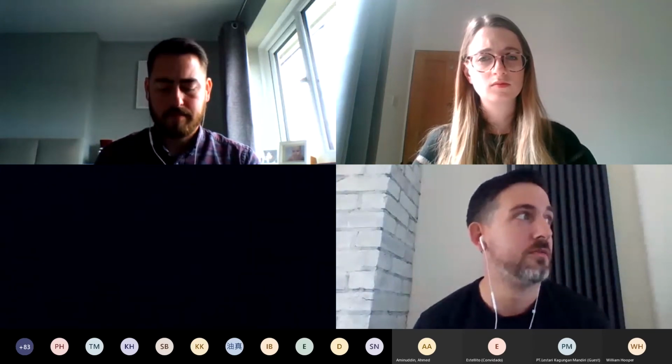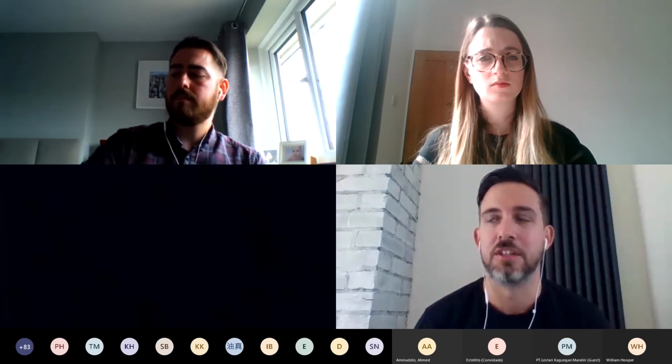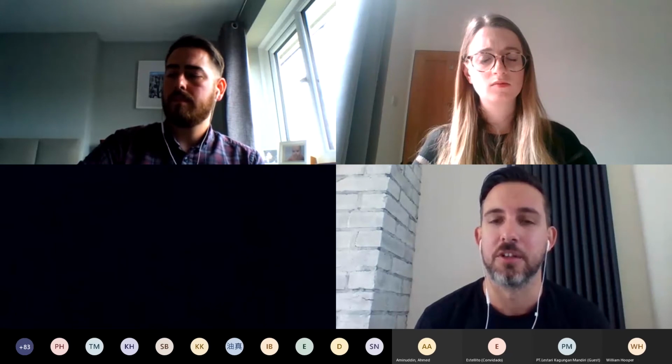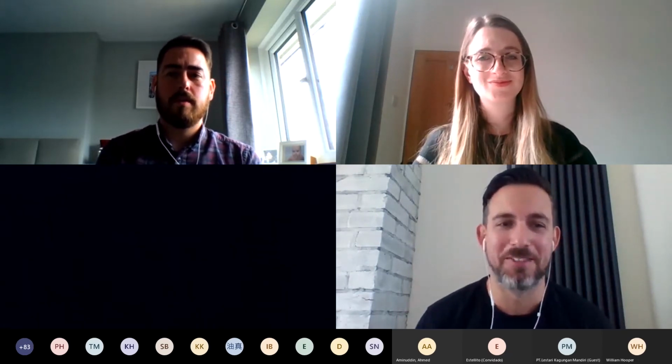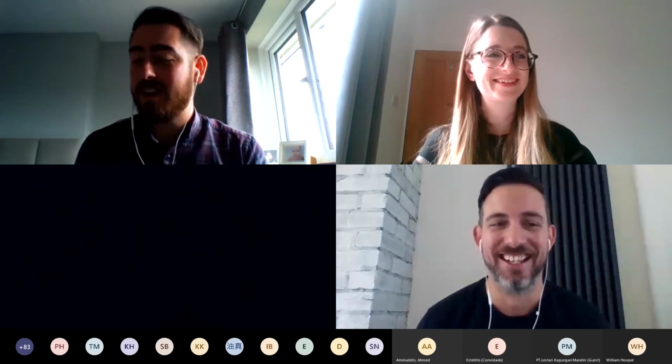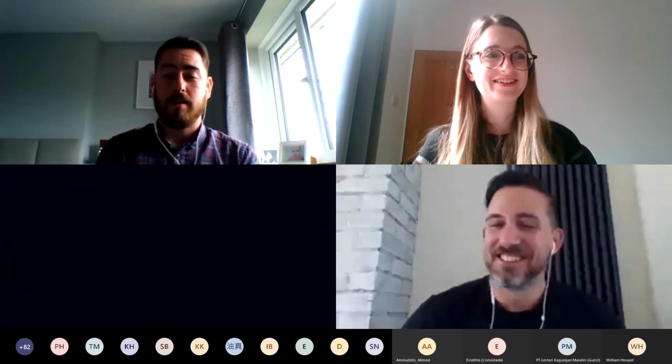So you need to review your application, review the type of cable that your gland's been installed onto, review your type of protection concept, and choose the appropriate gland for the installation. And was that the answer you were going to say, Matt? Pretty much. That's essentially all set out in -14.